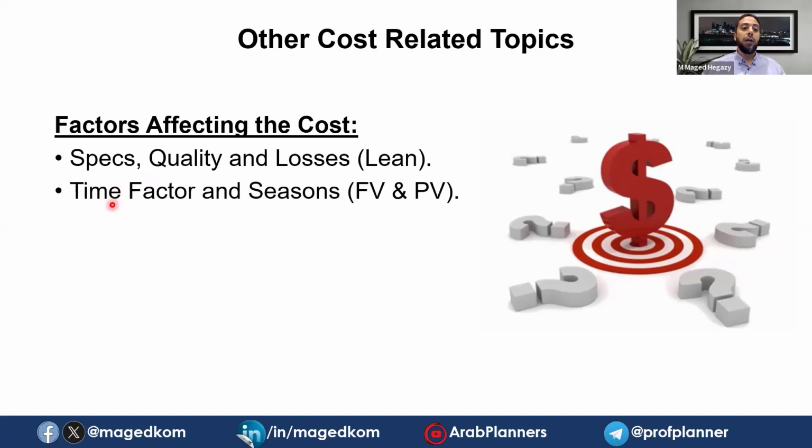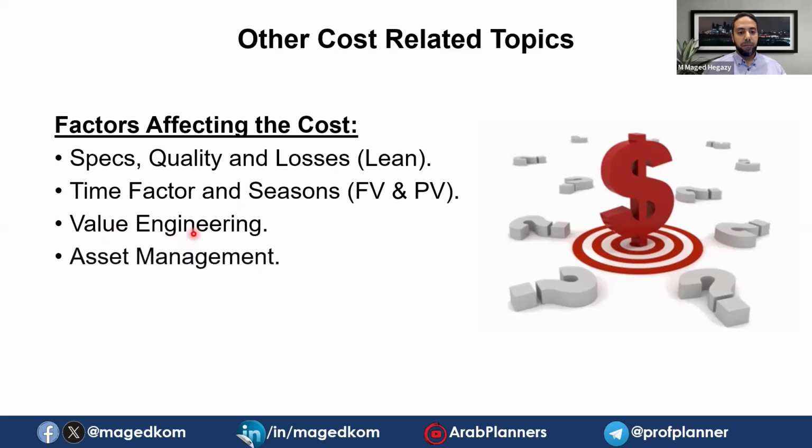and you price accordingly. The time factor, sorry, the time factor when you are going to execute this work, whether you are executing it soon or in the future, after a few years, and the impact of the time factor and the seasons. Sometimes you do items in different seasons with higher prices. Value engineering is one of the things affecting the cost, to do the best function, the optimum function, with the optimum cost.